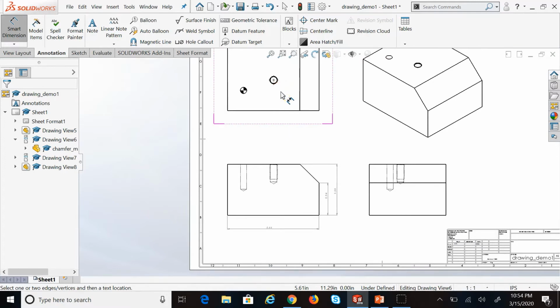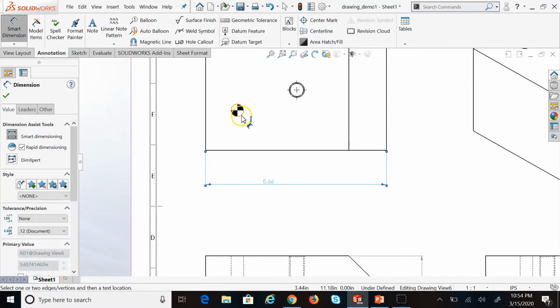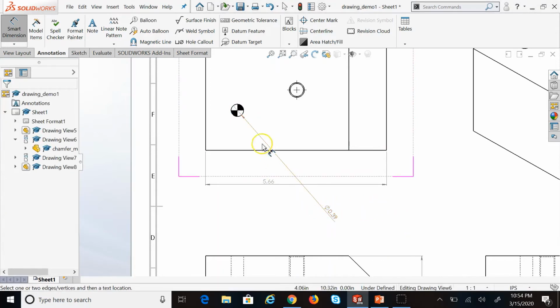especially when you have a combination of linear and circular dimensions, it's really easy to get them crossed. For example, here, if I click on this edge and provide width, and then click on this diameter and provide diameter and do something like this, you see now this leader, which is a dimension line, is crossing the other dimension line at this point. This is one of the things that you always want to avoid in any drafting. No two dimension lines should cross each other. That is an absolute must. So what should I do? I should move this radial dimension elsewhere so that they don't intersect.